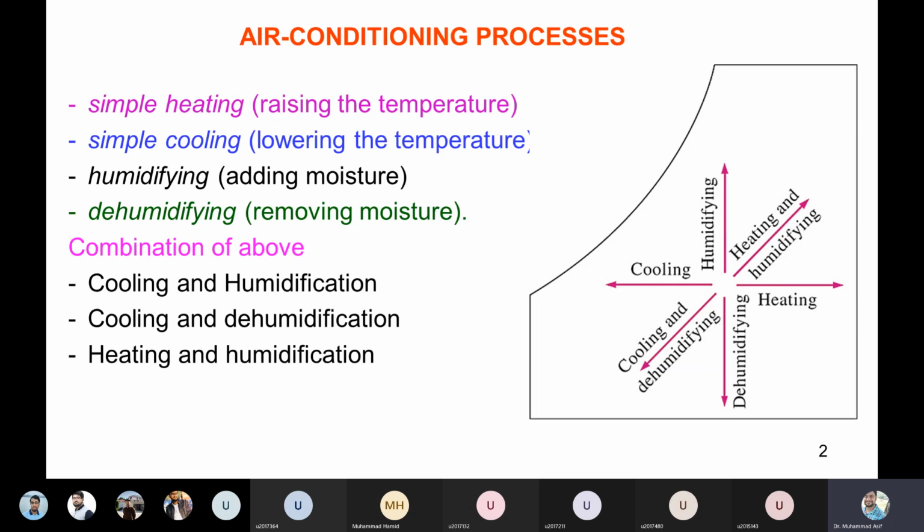Now, the psychrometric chart basically gives you an approximation. Some of the data may not be exactly pointed out on the chart. For example, if I ask you to figure out the properties of the moisture at 49% relative humidity, there is no line of 49% relative humidity, so you have to make certain interpolation between the 50% and the 60%.